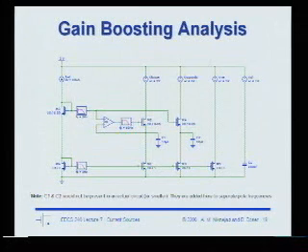Yeah, I noticed that there's two low pass filters? Yeah, so there's two more filters here. And is that practically used in the industry or is this actually not practical? This is just so that we can isolate the noise of these transistors and neglect the noise of the bias, because we just want to see that. But in reality, of course, it's pretty hard to build a filter with a 1 Hertz corner frequency.